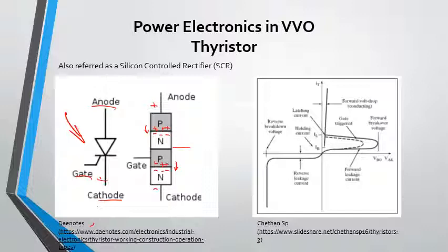This junction over here is still reverse biased, because since we're applying a high voltage on top, that means a lower voltage at the top of this junction, so the bottom must be a higher voltage, and here that means we have a lower voltage. When we apply a voltage through the gate, we are raising the voltage of that P section, which means we now have a higher voltage and a lower voltage here, allowing the current to flow through.